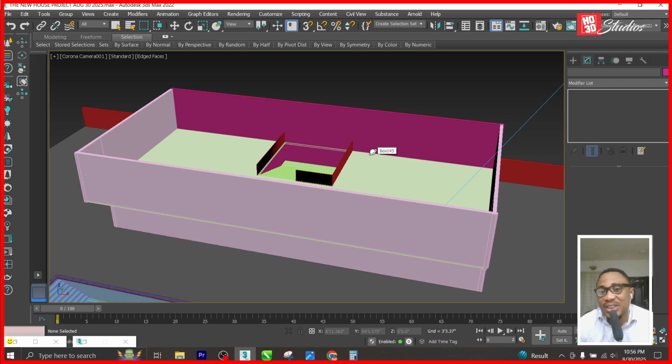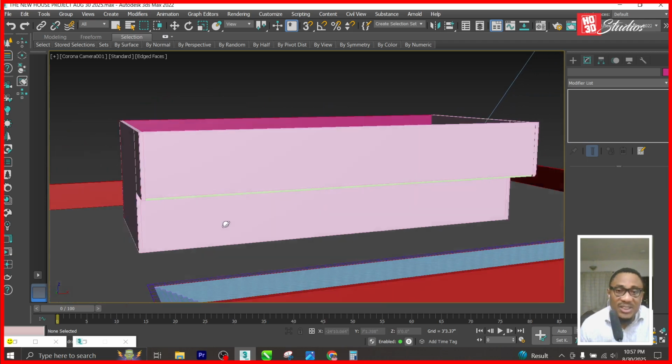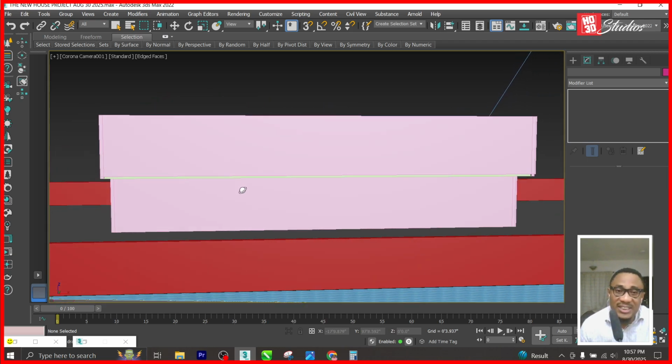Then a civil engineer slash builder would follow the recommendations of a structural engineer and put pillars here. For example, there might be, say, 8 pillars at the back here, or 6 pillars this way, of a certain size. You may say, you know what, this cantilever is just too wide, 100-foot cantilever, put a pillar here, put a pillar here. All right, anything, the structural engineer would be the one to do all that.